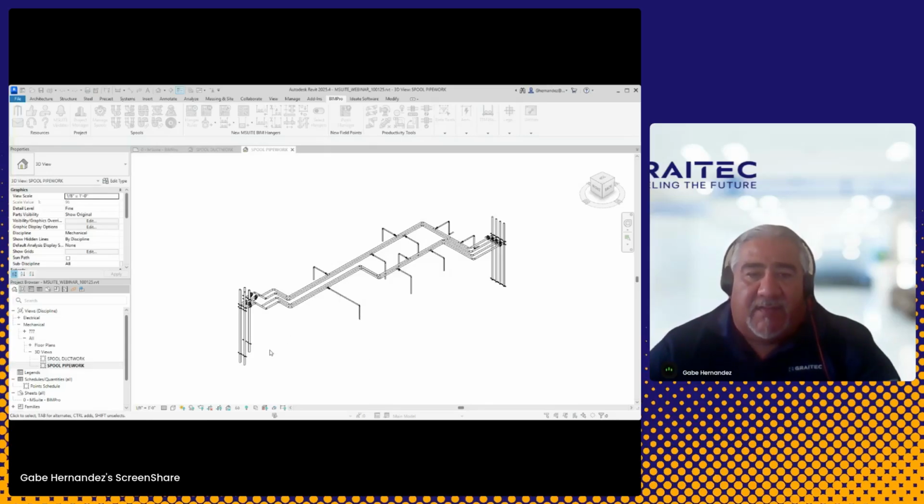And then, of course, there's some other options here to place in a joint between pipes, couplings or joints, and then creating single element spools from fittings and accessories, and then create spool sheets for created spools. So there's some check boxes in here. If the weight or elevations for any spool elements cannot be found, this clause will be ignored for that spool. So you can check those check boxes if needed.